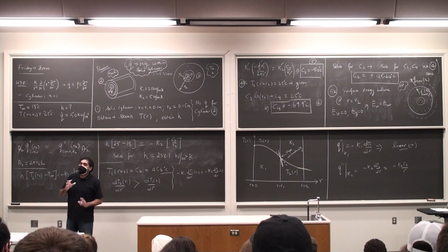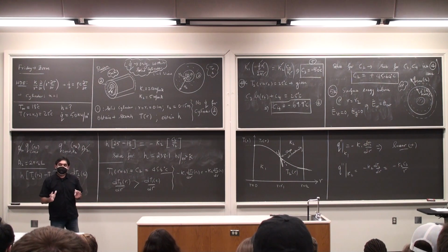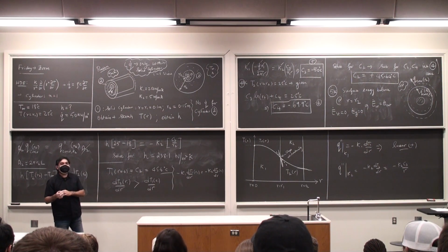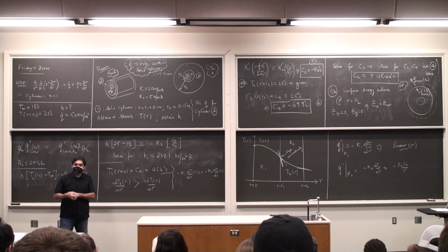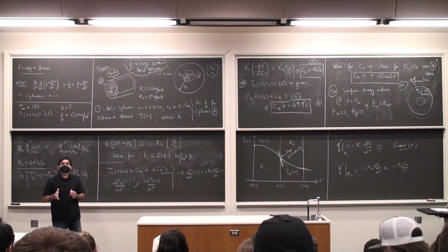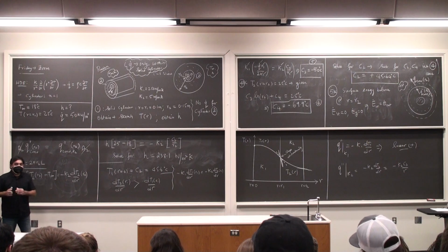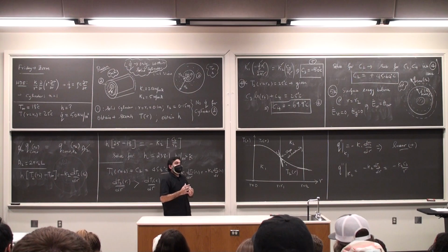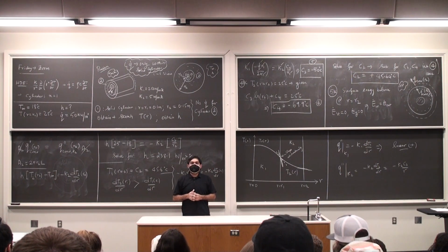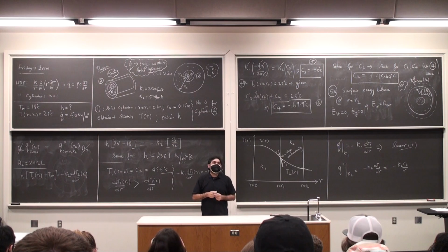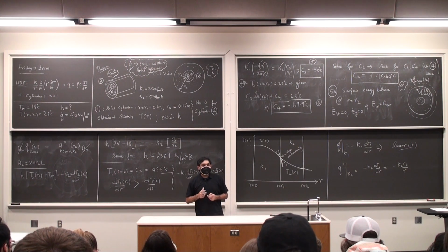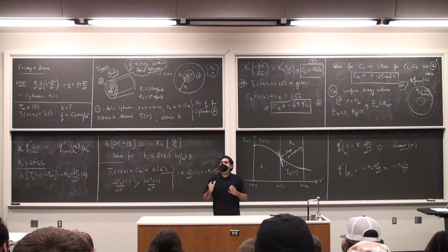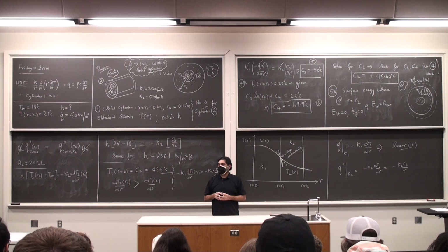And this is possible only when the heat generation is zero, because you want to have a constant flux, and only then can I talk about the idea of a thermal resistance. Otherwise we can't talk about this. If I have heat generation, the idea of thermal resistance is nonsense. Okay? And we will go to radiation in some time. We still have some time for that. You will see a different type of thermal network that is drawn there, which is different from what we do for conduction and convection heat transfer. And towards the end of the semester, we will combine all these elements together to have a total resistance network. Okay? Thank you.